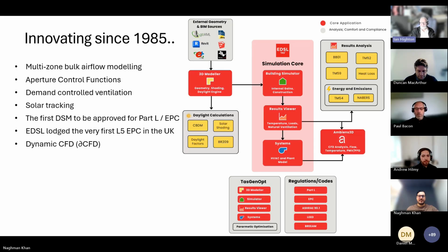Not too long. I mean, generally it's quicker than real time, but obviously if you're doing a complete atrium, that's going to be slower than a classroom, for example. But classrooms, you can get quite good results on a coarse mesh in 15 to 45 minutes. So it opens up CFD to being more of a design tool rather than just a post-processing event where the design's completely fixed at that point, and you're really just using the CFD to produce a pretty picture for the client, and it's just, oh, that's 2 p.m. on Monday afternoon, and that's it.